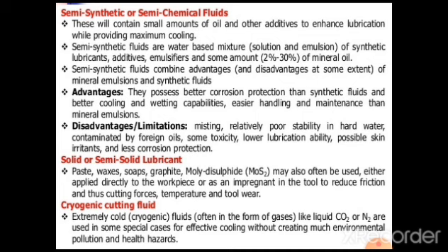The cutting fluids may be classified as solid cutting fluid, liquid cutting fluid, and gaseous cutting fluid. In solid cutting fluids, you can have graphite, molybdenum disulfide, stick waxes, bar soaps, and tallow in conjunction with fatty oil and sulfur. In liquid cutting fluids, water can also be considered, straight oil, soluble oil, chemical additive oil, chlorinated cutting oils, and sulfurized cutting oils. All these come under liquid cutting fluids.